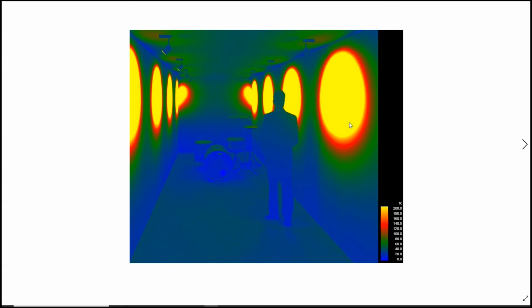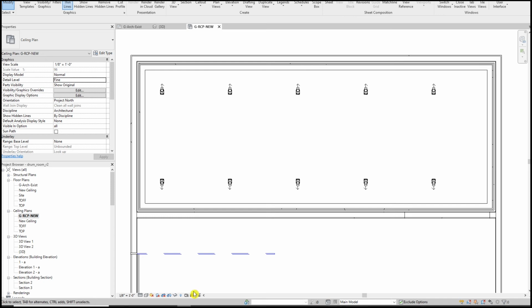You've got a giant spot on the wall that's above 200 foot candles. And then at the floor level, you're dipping down into 20, 30, 40. I mean, you might be okay if you were to judge it against, say, an office or something. But what I think this highlights, and it's intuitive, and you can see it in the previous image, is there are just giant spots and then a bright light and then dark. And so, that's great. With this tool, you can test things.